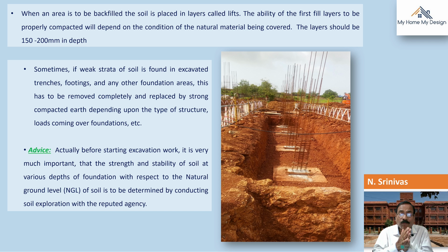The weak strata, sometimes whatever the available material digging for the earthwork, sometimes you might have seen loose soil or filled up soil which occurs during excavation. That type of soil, already filled up with loose compaction, is not best suited for the structures for the backfilling.